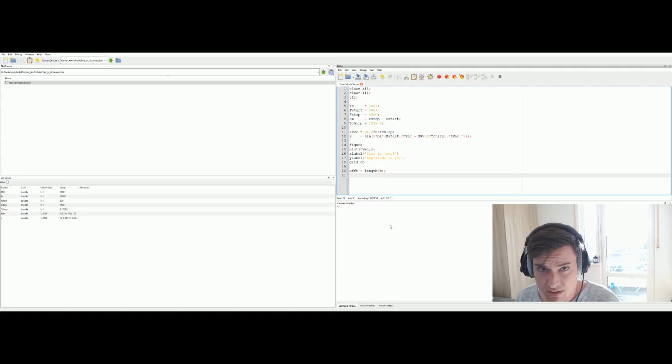And to plot the signal, we need a frequency vector. Here in the time domain we created a time vector to plot our time domain signal against, and now we need an F vector to plot the frequency domain signal. We start at the negative frequencies and we go up to the positive frequencies, and normalize it.